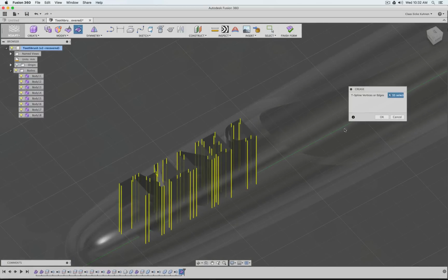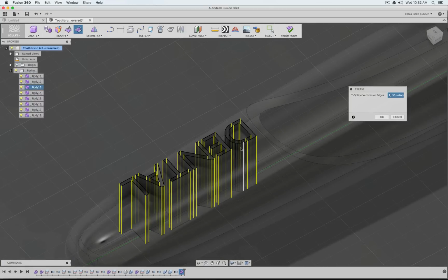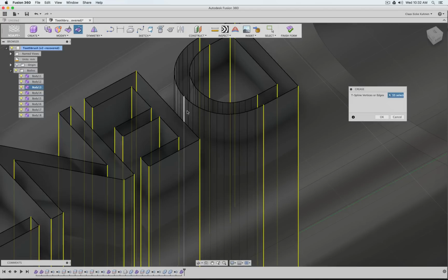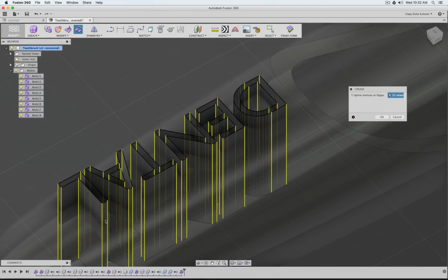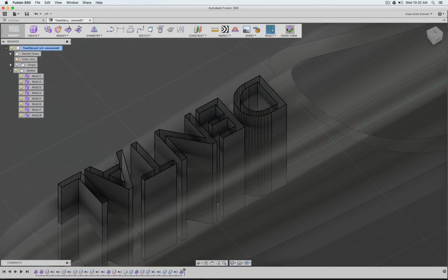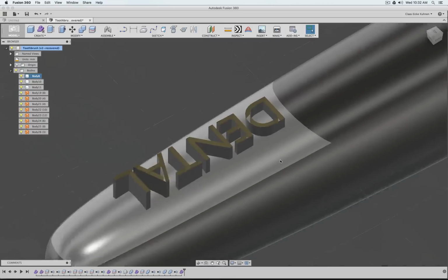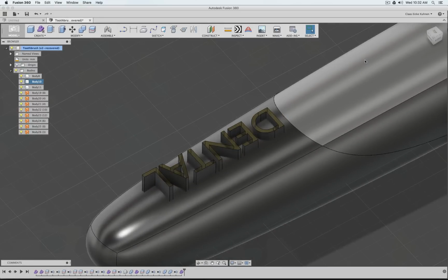Okay. So why did I actually bring this over into TS and not go via a base feature and then edit the flat geometry? The thing is then my letters would be very faceted, and I want this to be round. So in this case, because I had a letter extrusion, I can easily crease all these few simple edges, and I have straight letters back, and then keep the rest with the D, for example, nice and round.